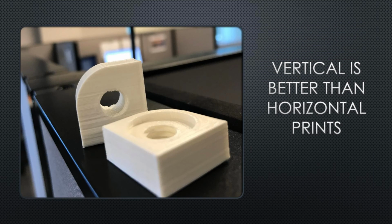Also, if you remember the orientation in which I brought it into the MakerBot print, vertical is better than horizontal prints. So if you lay your 3D printed thread vertically, like this one closest to the camera here, it's going to give you a better print.